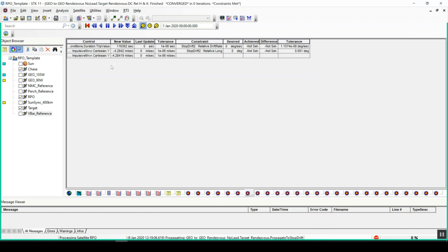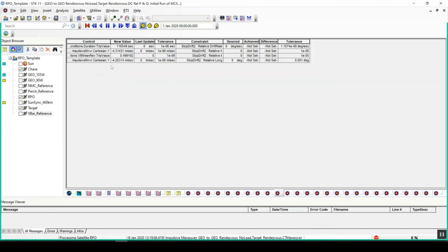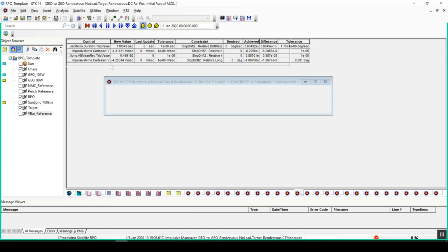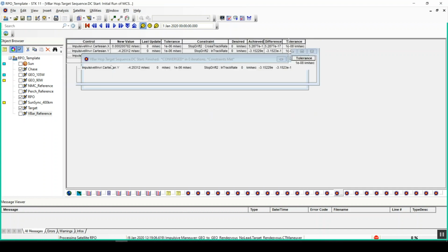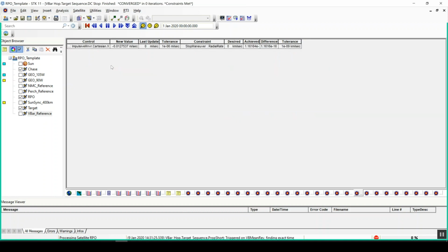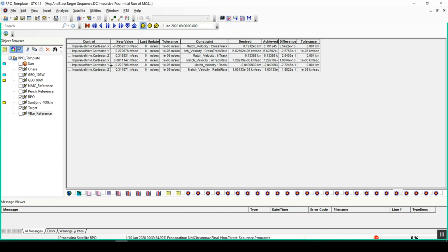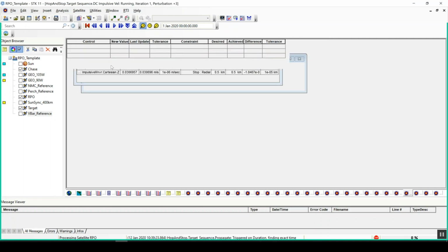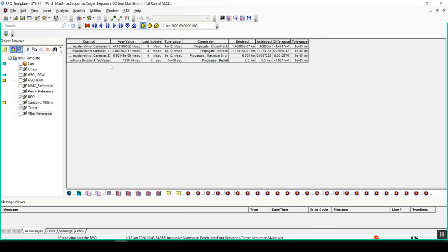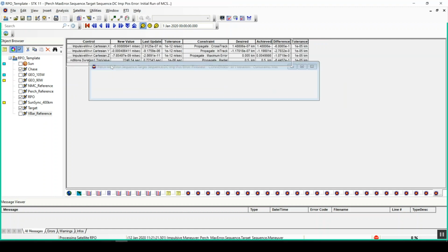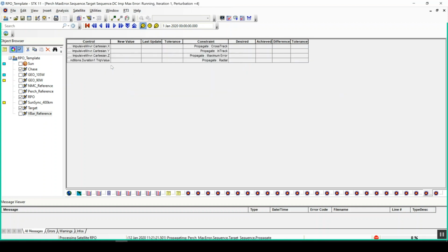This is what it's going to run through, every sequence. It's going to be one continuous mission from being the chase initially, 15 degrees away in the geobelt in a stable 90-degree west orbit there, non-drifting. And we rendezvous onto 105 west, onto a V-bar of a satellite sitting at 105 west. Then we performed a series of steps in our proximity operation there, starting with a V-bar hop, a natural motion circumnav, a hop and a perch.